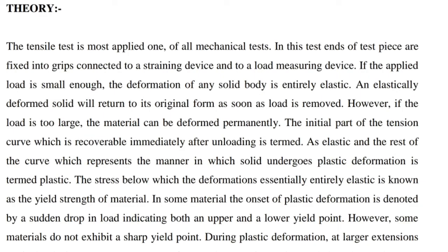Theory: the tensile test is the most applied of all mechanical tests. In this test, the ends of the test piece are fixed into grips connected to a straining device and to a load measuring device. If the applied load is small enough, the deformation of any solid body is entirely elastic. An elastically deformed solid will return to its original form as soon as the load is removed. However, if the load is too large, the material can be deformed permanently.